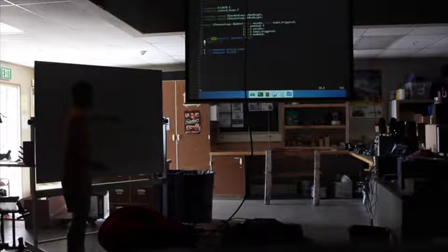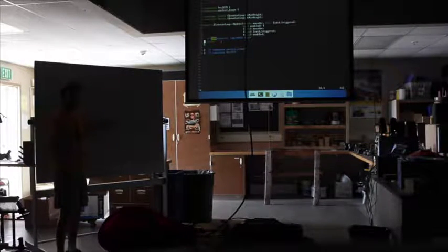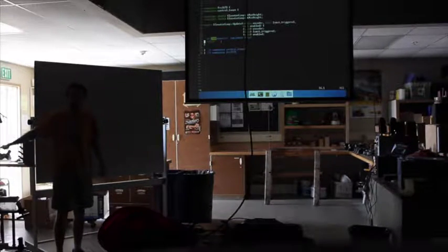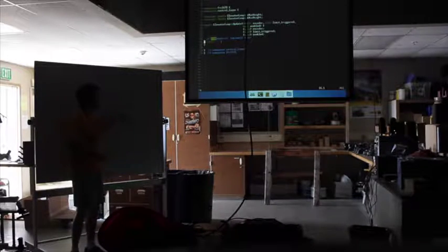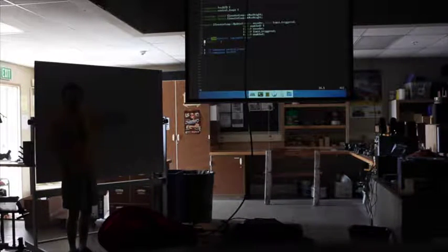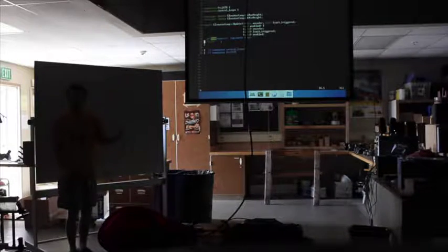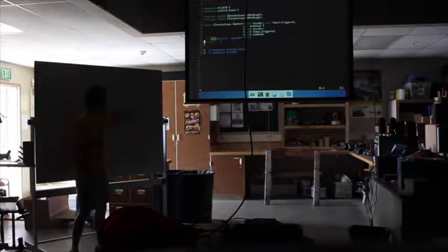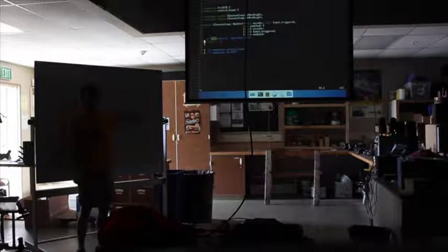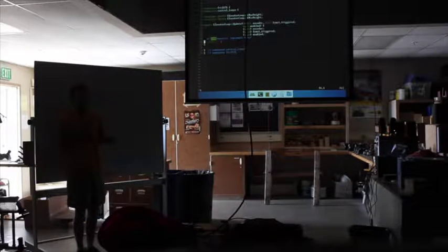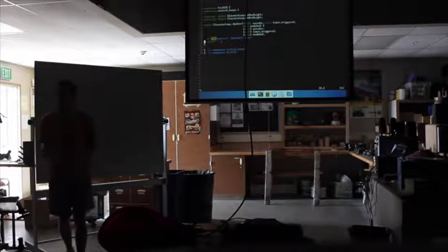Out to our hardware. So this box here lets us, the driver will say, hey, I want to go up here. And then this box says, okay, I'm zeroed, I'm going to give that to you. Or I'm not zeroed, let me first home. And then I'll give you your goal. And then it can command a goal to the PID loop. So the PID loop can then move down in a slow, controlled manner to 0. And then once we found it, we could implement motion profiling or something, or we could just jump to the goal.